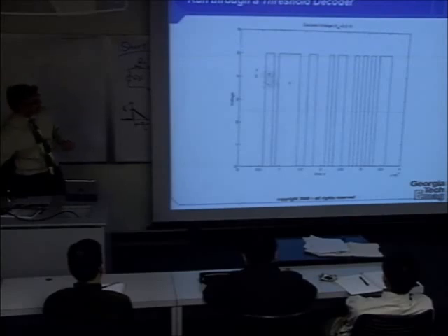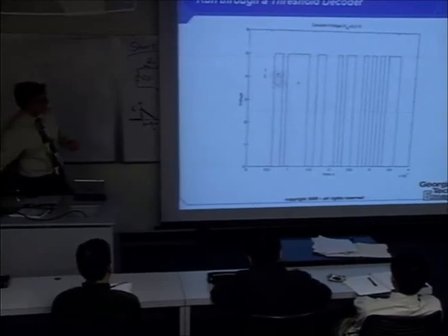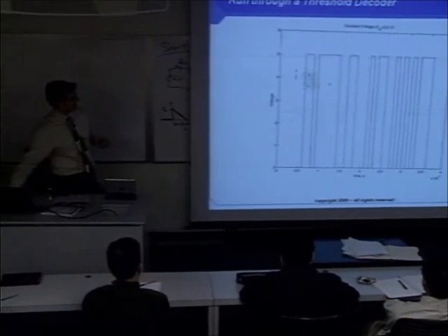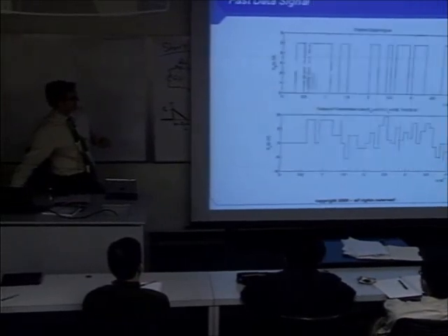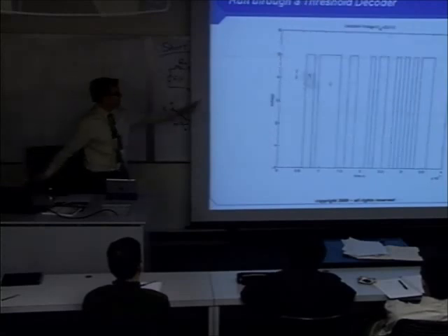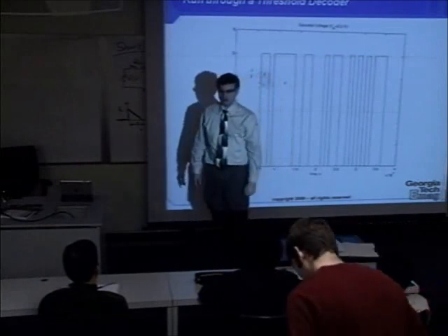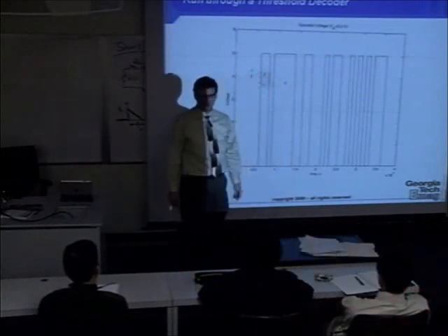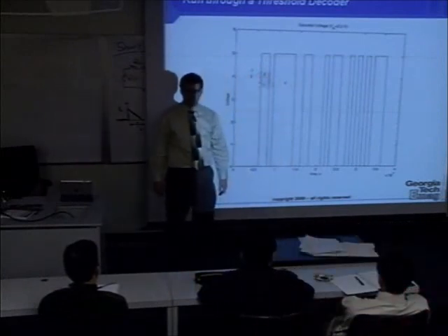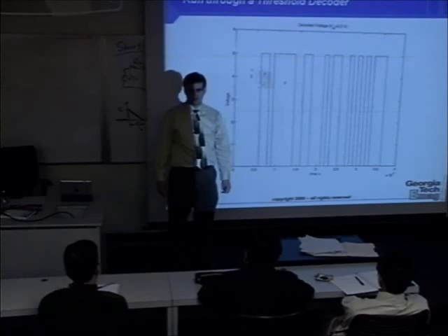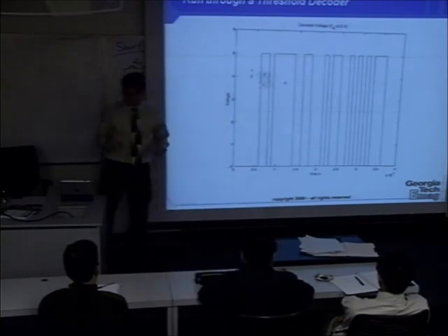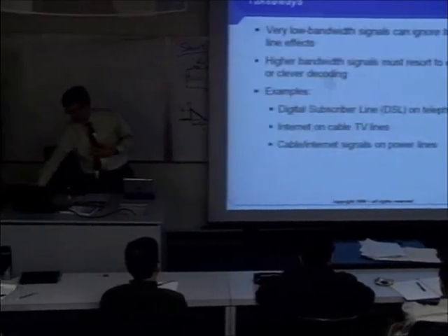So that's actually the decoded signal with the threshold decoder. Notice it looks nothing like the original signal that we sent. It kind of looks like it up front here, but then it just starts to oscillate as all that intersymbol interference distorts the decoding. We would need some really serious signal processing and waveform design in order to get that channel to work as a proper data channel. Any questions so far?